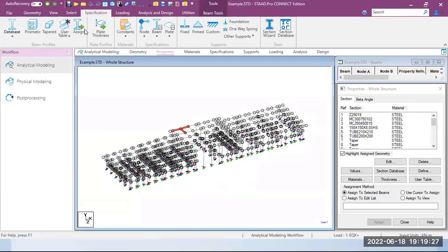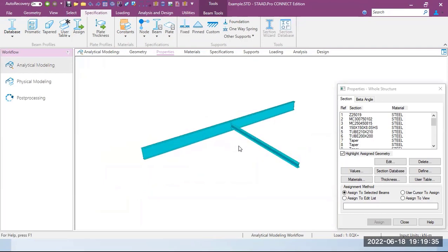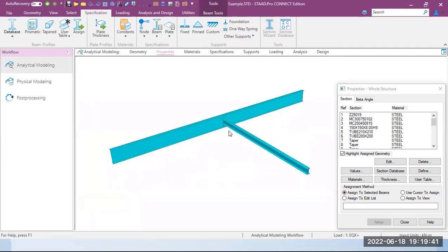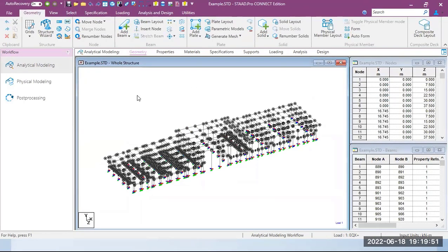How can I hide this? This is the rafter of this main frame, and this is the strut member. What I did here is release this member, so this connection will be nothing but a shear connection. We have not released any member along the width of the building.